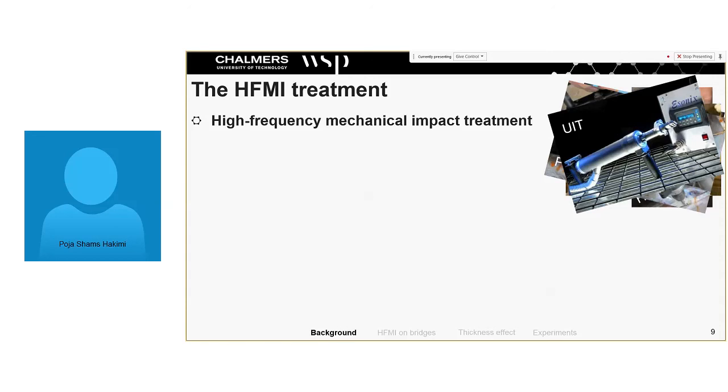It is also very case specific. So if you want to repair a weld where you can already see a crack, but it's a shallow crack, then you might need to first grind away the cracked, damaged area, and then you can perform this treatment afterwards, which has also been researched and looks promising. Thank you.